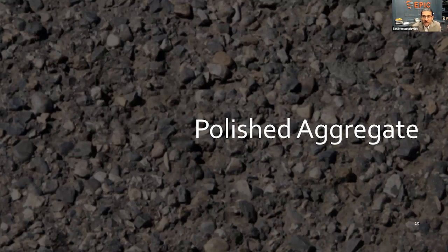Again, like I said, it's going to be exposure of the fine and coarse aggregate above the pavement surface. And with the repeated events, more polishing is really going to occur in high traffic areas as opposed to low traffic areas. But I'm sure within a pavement system that we all drive on, that we all see every day, you're going to be getting a mix of different issues, even on your drive to work, your drive home, of polished aggregate.